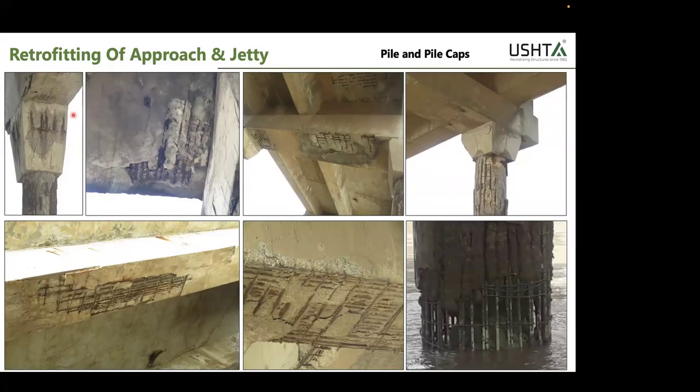So what happened here was they kept on repairing the concrete structure without treating the root cause. Now the root cause is corrosion, chloride-induced corrosion. Let's dive a little deeper into the process of corrosion. Whenever we are casting our concrete, the pH value of concrete is around 13.2 to 13.4. It's highly alkaline. Over the period, as the pH drops, carbonation will be there, and there will be corrosion. And especially in this case, it's chloride-induced corrosion.